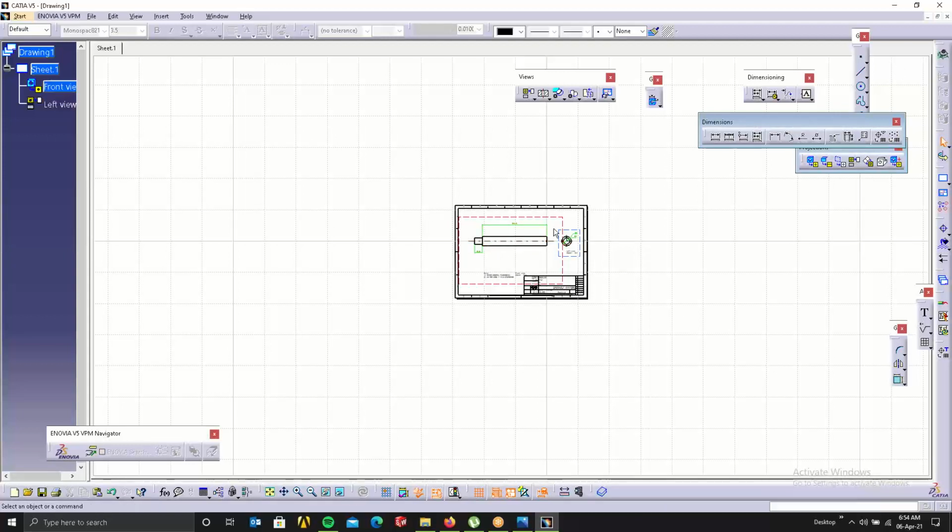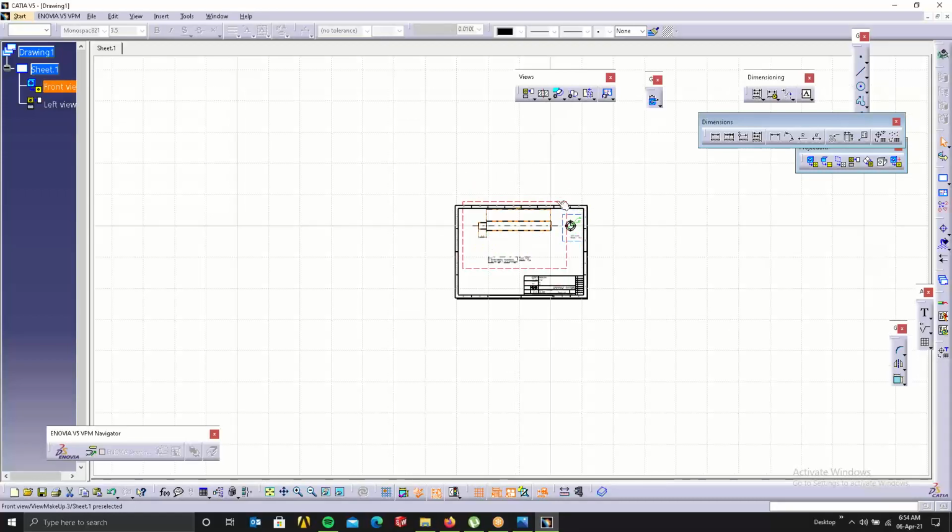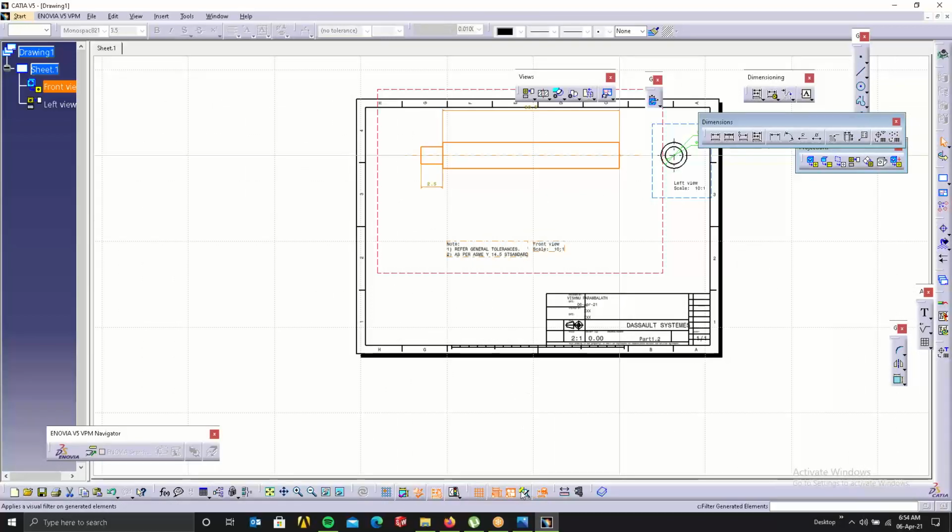Then here you can see this red line and blue line. So that basically helps you with all the positioning and everything. So sometimes what happens is you won't get it. So if you look down, here you have display frame. So if frame is not there, you won't be able to move it. See, I'm not able to do anything now. So that's why you require this. Turn this thing on. Then you can move it around.